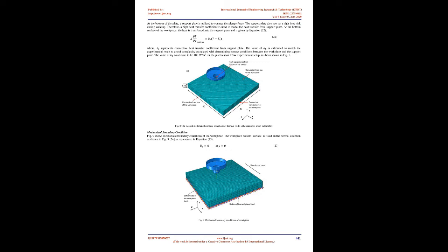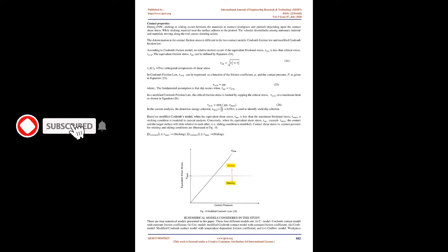The research work of Zhang et al. 6 showed that the friction coefficient significantly depends on temperature. Consequently, a temperature-dependent friction coefficient that varies in the range between 0.2 and 0.339 was used in the analysis presented in this paper. The values of the friction coefficient in the current analysis are listed in Table 3, which shows that as the temperature rises, the friction coefficient is constant up to 300 degrees Celsius. However, after the temperature reaches 300 degrees Celsius, the friction coefficient starts decreasing. Zhang et al. 6 explained the choice of friction coefficient in the flowchart shown in Fig 4 below.